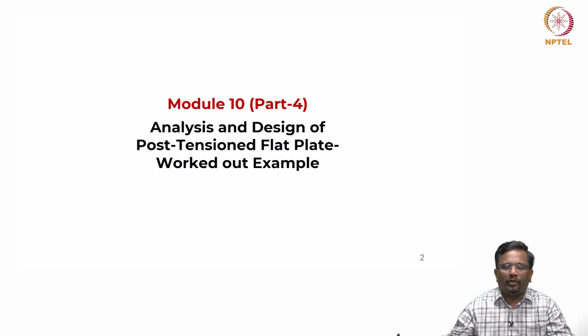Particularly, we will take a real case, a PT slab, and we will go through how we do the preliminary design and at the same time how you arrive at the equivalent frame properties. Then we will also look at how our manual calculations using the equivalent frame method compare with the results of commercially available software.